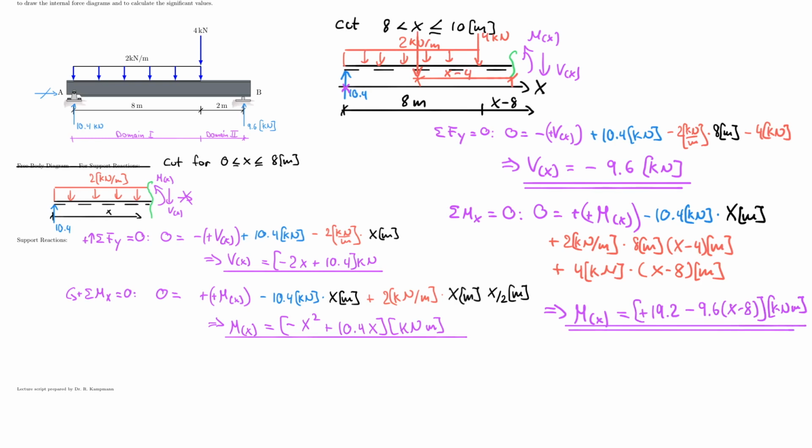And if you now wonder why I did this without doing a lot of calculation and really solving the entire equation above here, of course, I could have calculated all of this out, and I probably would end up with something written in a different way, but that would result in a very similar answer. It is because I can verify that I have a moment that is 0 here, and I need a slope that is equivalent to 9.6, and that's where the 9.6x comes in.